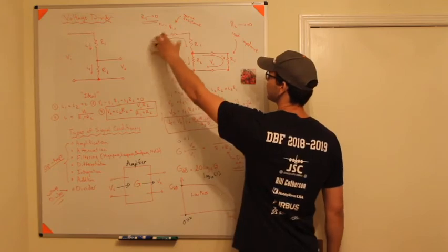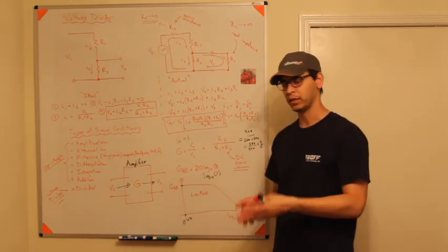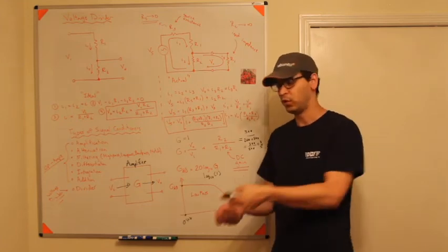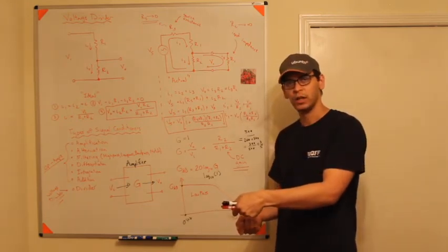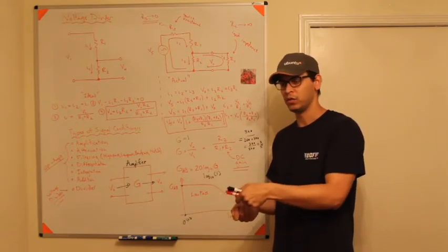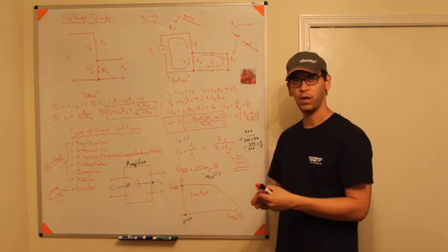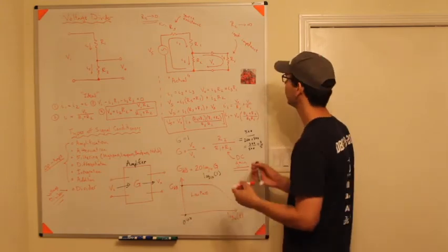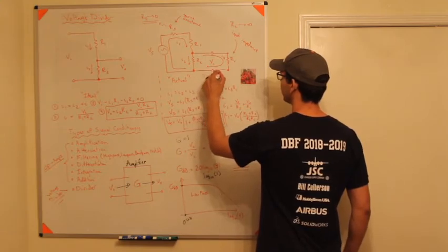So that source resistance is there when you hook something up to it. Now if I have, say, an Arduino or a circuit playground or anything like that, or even a voltmeter, and I measure that voltage, I do not want to take any energy from the system. And remember, power is equal to I squared R.